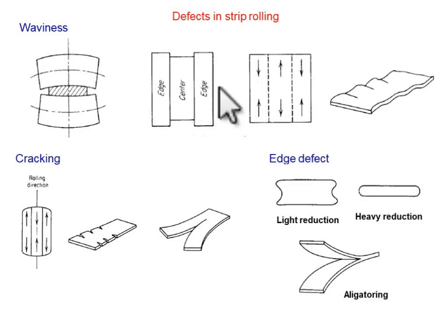Now the center S, this is also a defect of rolling operation, because the deformation of the center is higher in rolling as compared to the outer surface. That's why this happens. And again, cracking also occurs. If the material is not so ductile, then cracking may occur in the rolling operation. So these were some defects that occur in rolling operation. Till now we have covered all the different types of forming operations, and in the next lecture we will start with welding operations. Okay, thank you.